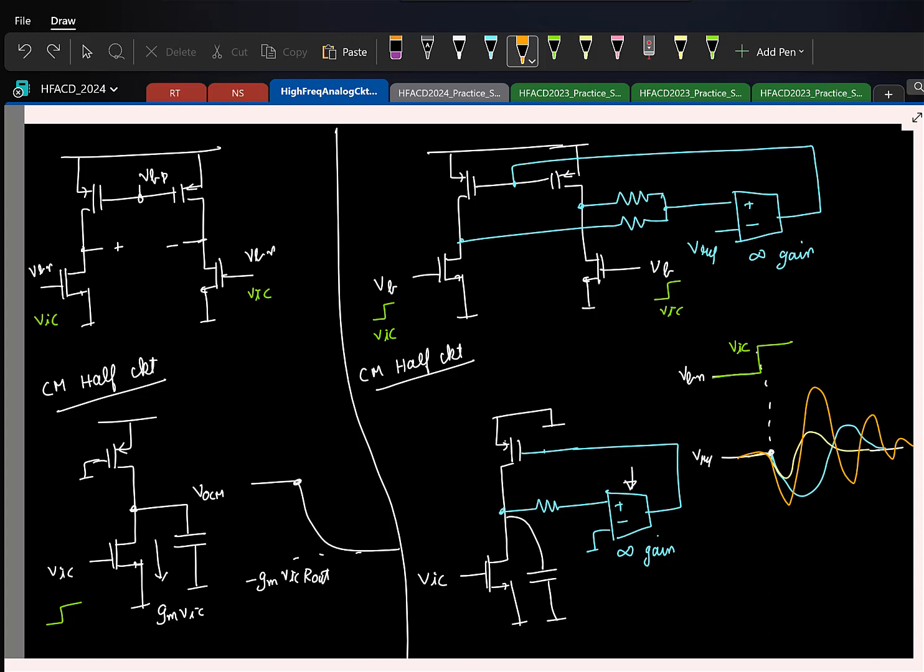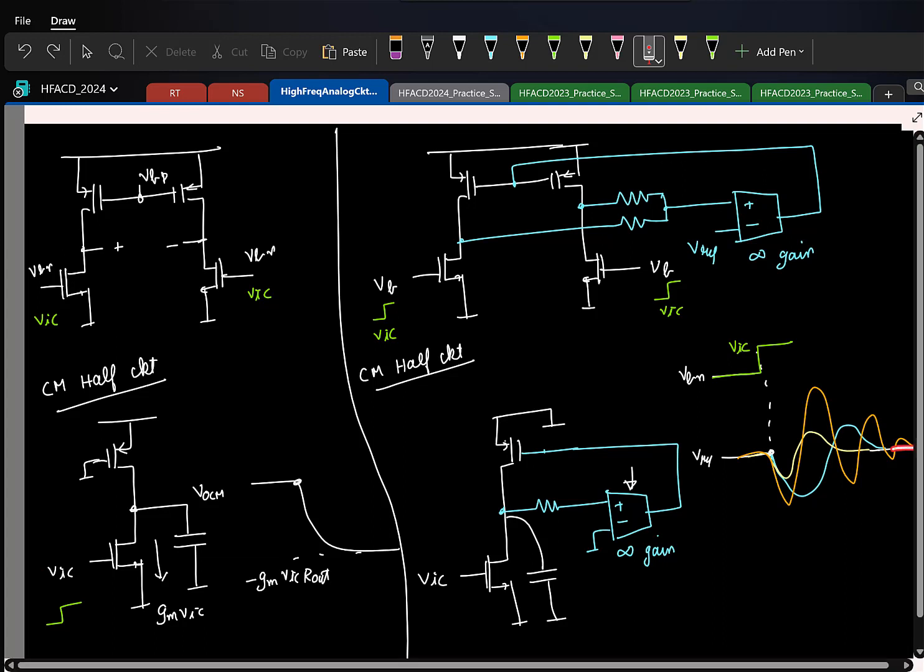Okay. So that's what we mean when I say that my common mode feedback loop has some particular phase margin and a particular omega u. This will quantify the way in which your system will respond to common mode changes. Okay. Right. So now, as you can see, this common mode feedback loop, in addition to setting your output DC bias to some value, is also making sure that if I have any common mode changes at the input, that gets suppressed eventually, right?